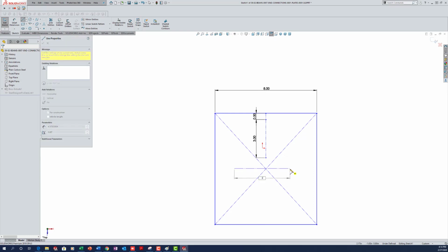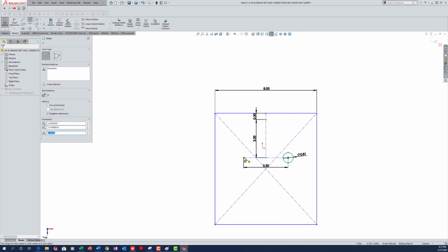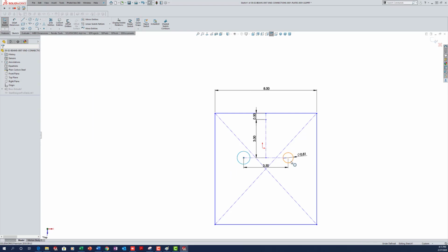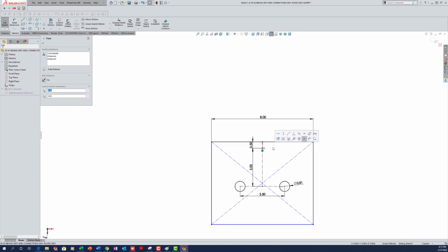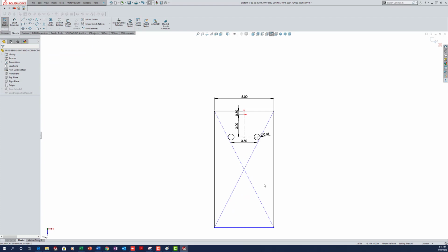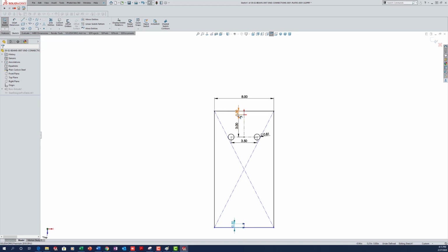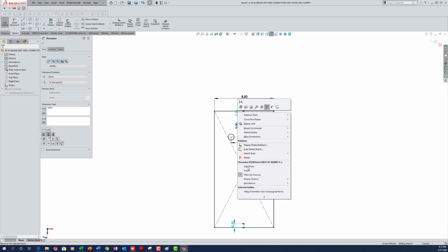Now I'm going to give the holes a space between them for a gauge line. And create the holes. Just make these two equal so they stay the same. This will come down and attach to the origin. This allows us to mate things in place. I'll actually add another line down here, center line, and link these two variables together, which later on, that will be handy.